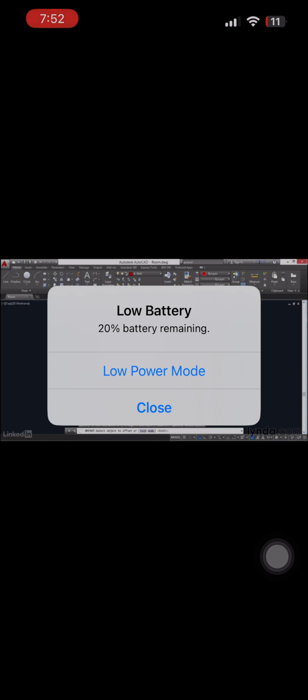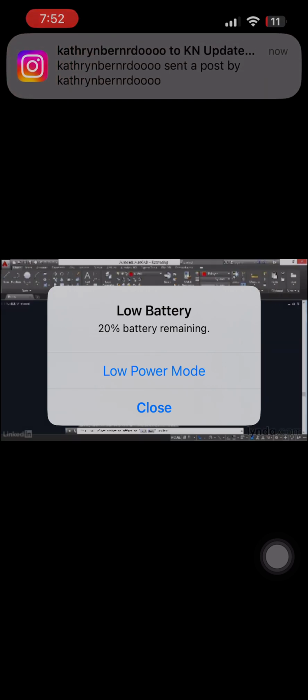Click on this line, and immediately you go to the next step. It says Specify Point on Side to Offset. Because the cursor is on the left of this line, it is giving me a preview image of the new object. If I move the cursor over here on the right side, I get a different preview. So if I click here, that object will be created.